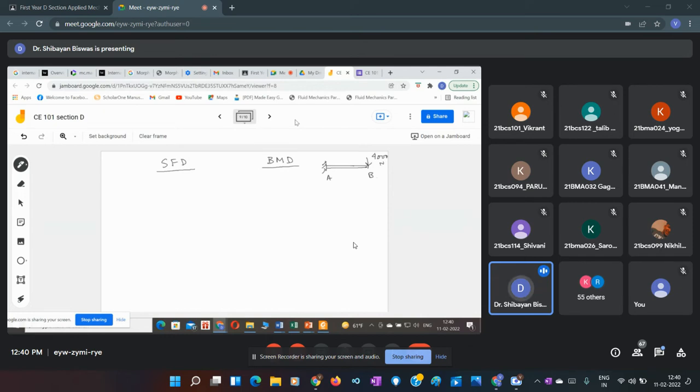What is that? We have to remember these parts, and please pay attention very carefully. So for shear force, the first step is to consider the left or right. Left or right. Okay, means take a section at any place you want.